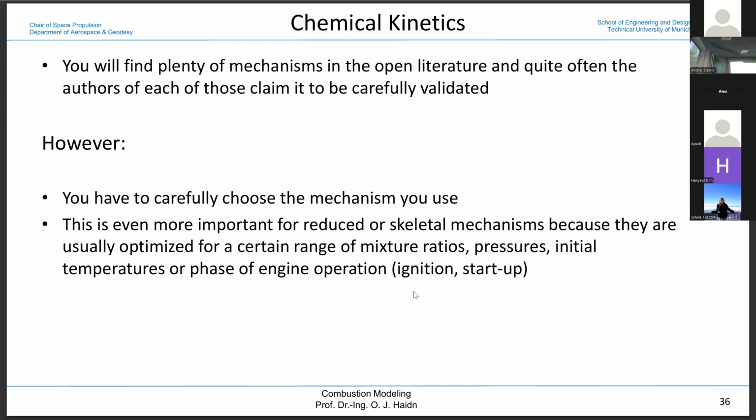Let's say we wanted to tune it first and say we are only interested in the ignition process, meaning that we do ignition under vacuum conditions, so that should be a couple of hundred millibar in the combustion chamber, and we want to ignite oxygen methane. So that was our first optimization goal. And then we said, okay, we want to have some upper-stage engine, so maybe 30, 50 bar. For Vinci, this is 60 bar.